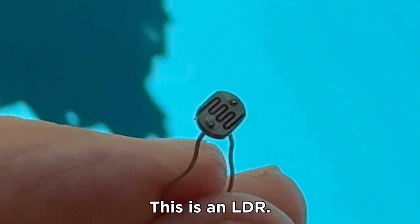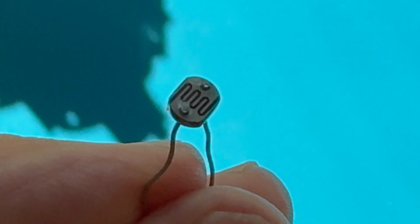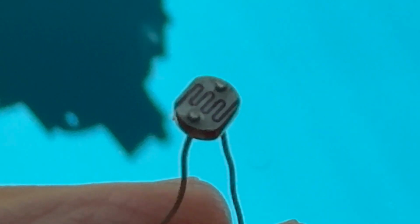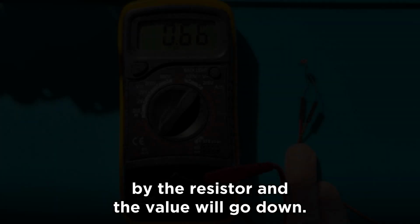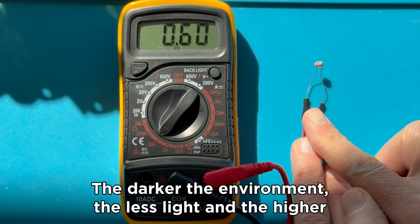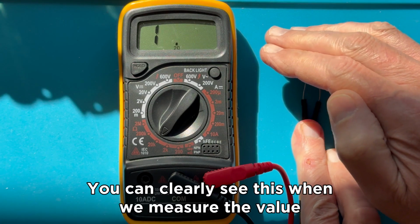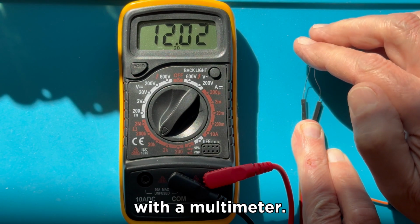This is an LDR. LDR stands for Light Dependent Resistor. It is a type of resistor that changes values depending on the amount of light that falls on it. The brighter the environment, the more light will be caught by the resistor and the value will go down. The darker the environment, the less light there is and the higher the value will be. You can clearly see this when we measure the value of the resistor expressed in ohm with a multimeter.